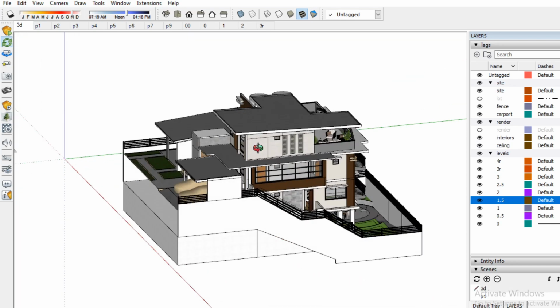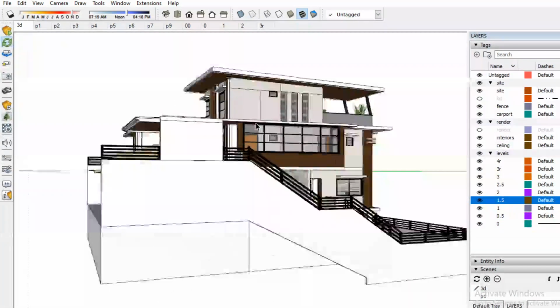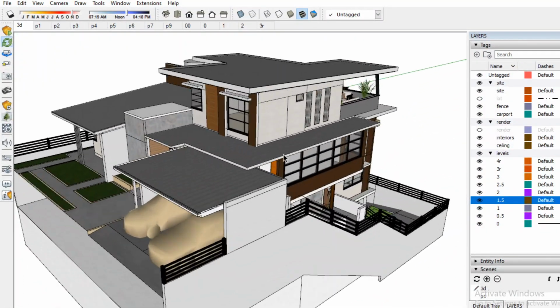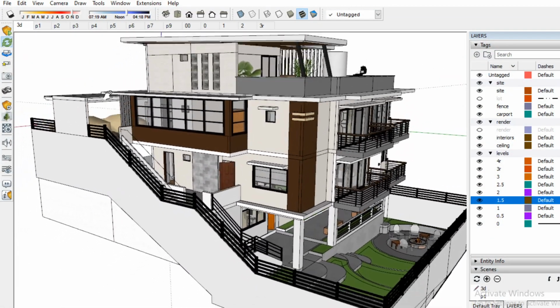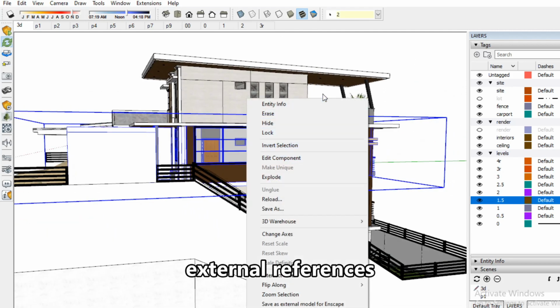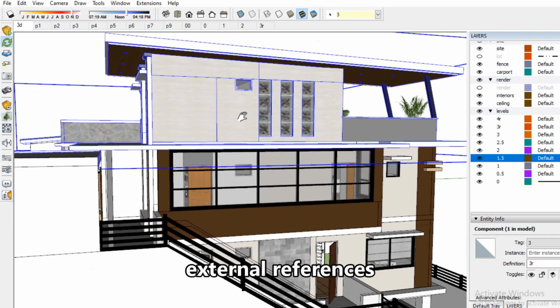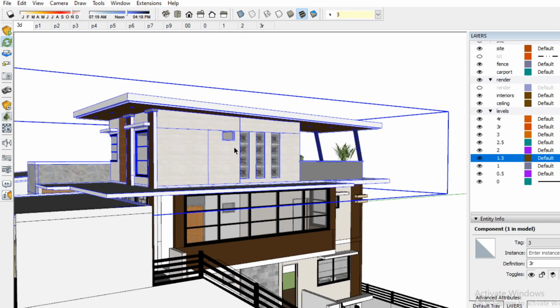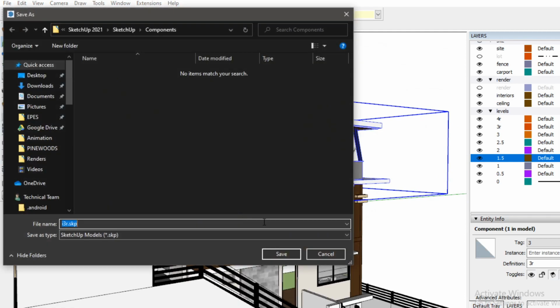Once the 3D model has been finished, you could start modeling the interior layout. I chose not to model the interior here yet, so that I could easily send this to Layout without lagging. Each level I turn into a component and name them their floor level. Say for example 3R, or the roof deck. Turn it into a component and save as.